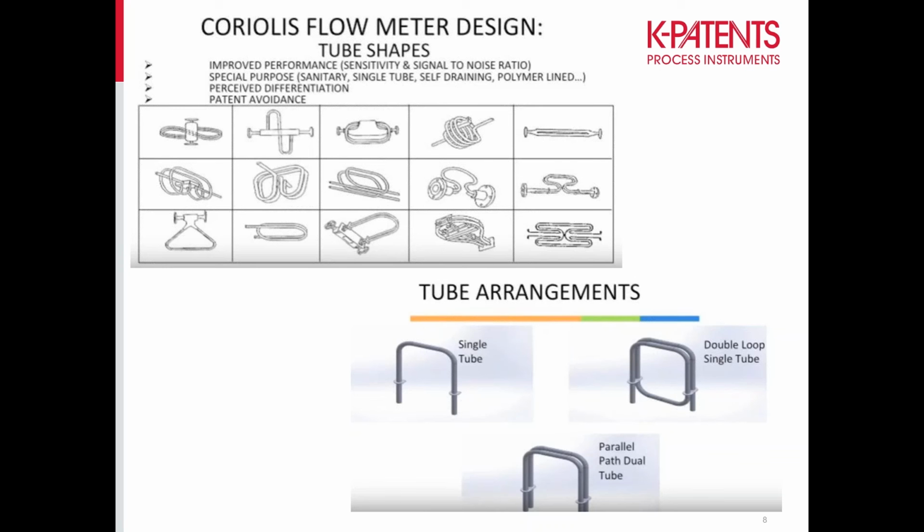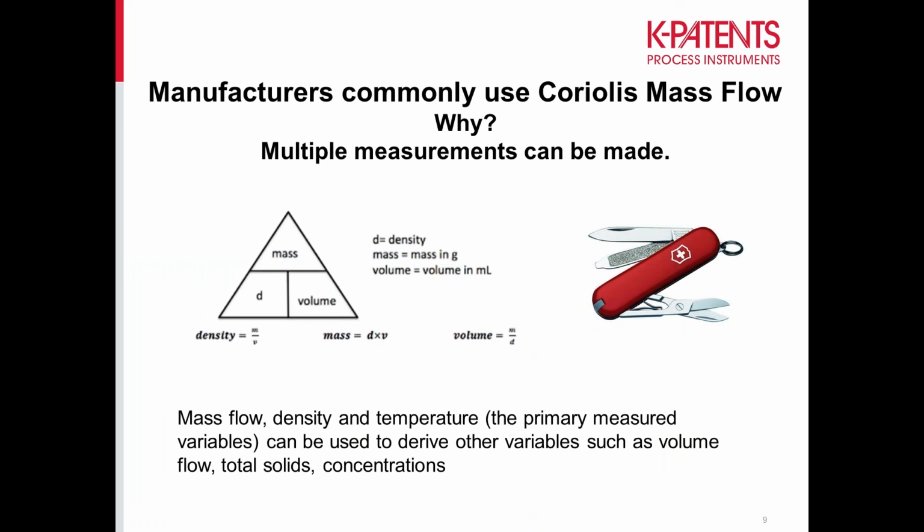However, where instrumentation is concerned, there's comfort in the familiar, but also there's a problem. When you have comfort, you know what to expect from that measurement, and the maintenance personnel know how to troubleshoot and recalibrate and maintain that specific instrumentation, because there's a lot of them in the field, and that's good. However, the downfall is that you might miss out on something better for the task at hand, and that is specifically a tool made for the task of measuring concentrations.